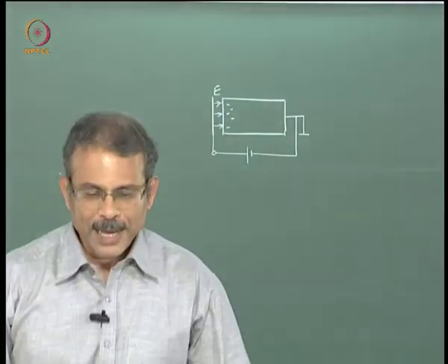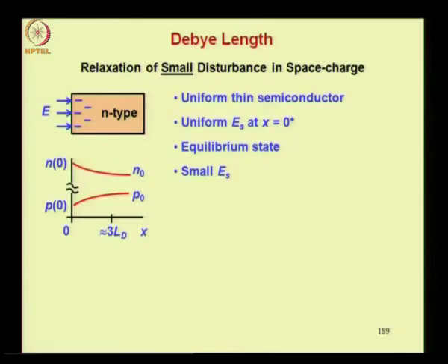So you will find in fact that the hole concentration reduces here. This is one more indication that these are not excess carriers. Why does the hole concentration reduce? Because it is the equilibrium state, n into p is ni square. So if electron concentration increases, hole concentration falls. We will discuss some details of this situation shortly.